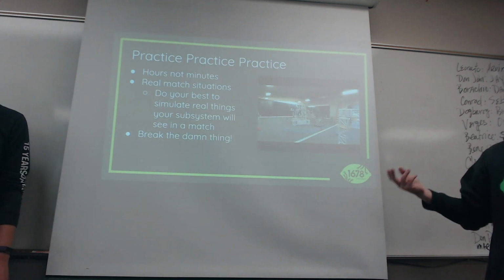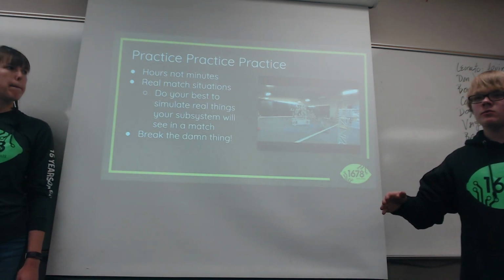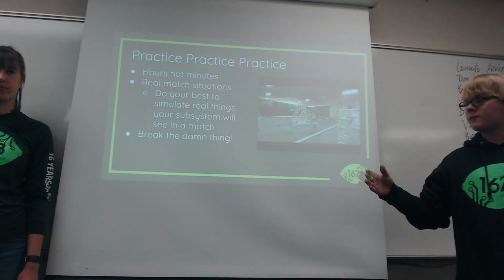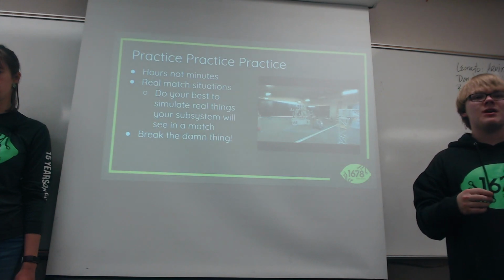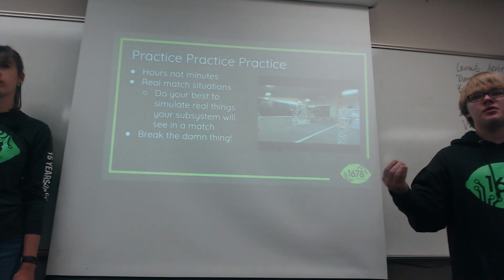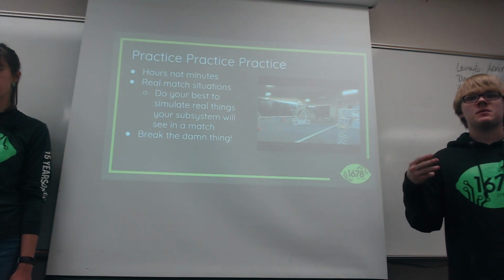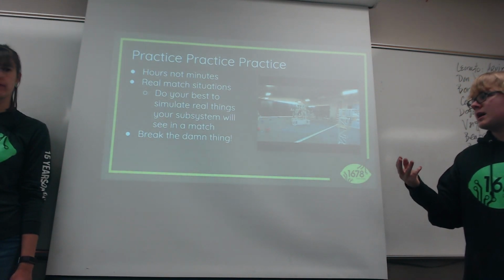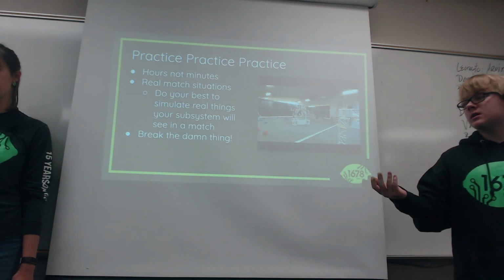And the really important thing is you want to try to limit test everything. So you want to know, if I send something through really fast, does it work? If I send something through really slow, does it work? If I send something through at a weird spin, does it work? You're basically trying to find every single possible thing that you can do to this mechanism to break it, to make it not work, to get something stuck. Anything that you can do to try to mess it up, do it. So you know if that happens in a match, are we okay or are we screwed?